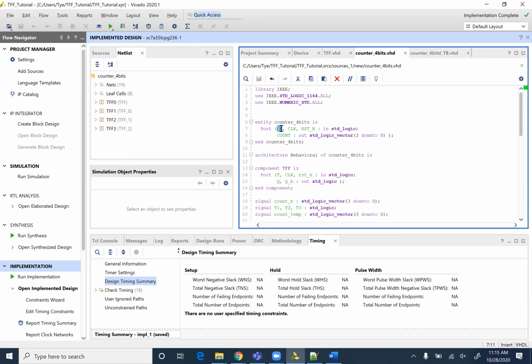But you also need the other things in your constraints, like the clock. You know how we had that one? Yes, W5. The clock, in this case and in many FPGAs, is actually physically tied to a pin. So to get the clock, I tie it to W5 in our case, because W5 is a 100 megahertz clock. Now that can happen one of two ways.